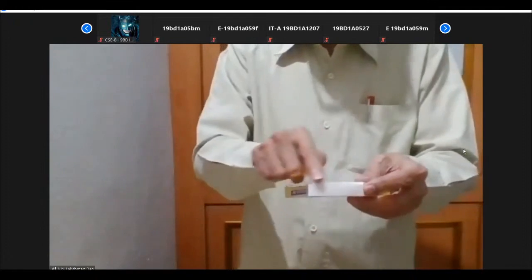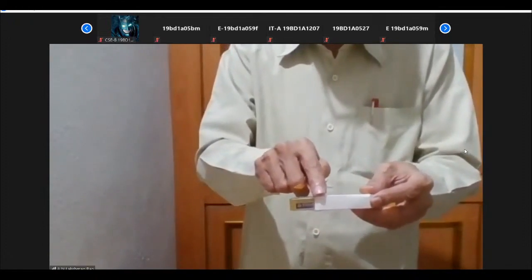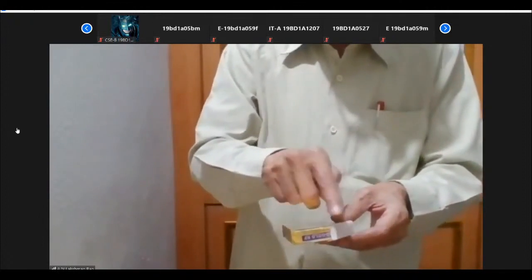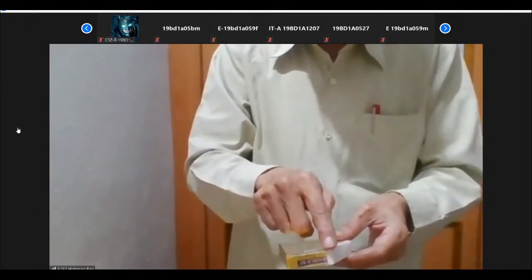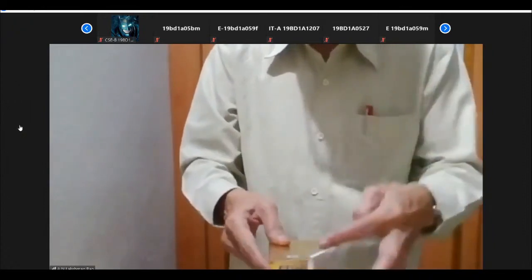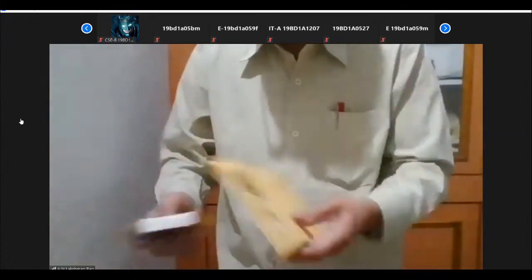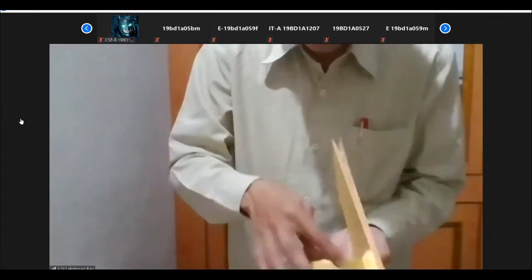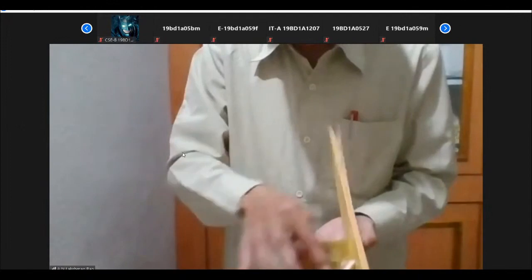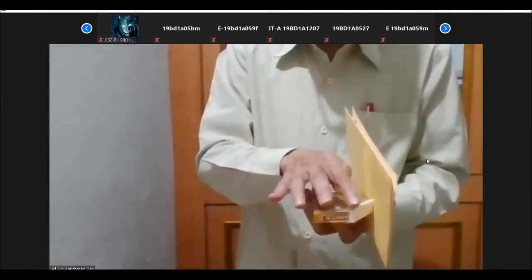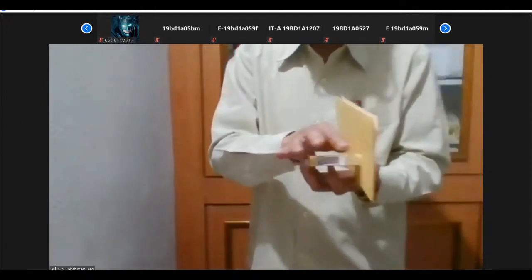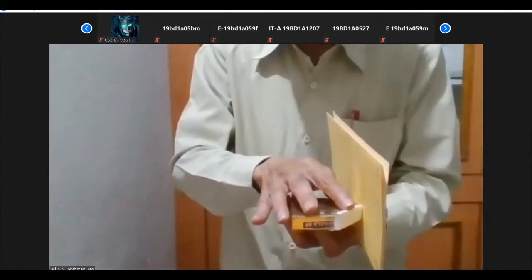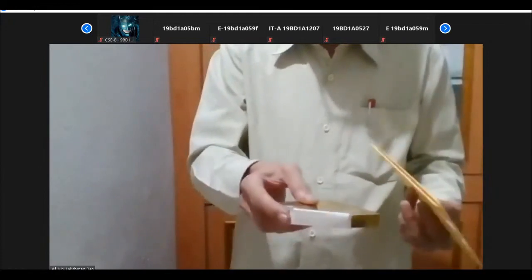Now I have to draw the true shape. And if you see from top, you are seeing only 20 mm. That is called sectional top view. Dear students, it is 50 mm, 50 minus 30, the white portion is only 20 mm. I am saying 20 mm here. This is called sectional top view. And this is true shape.